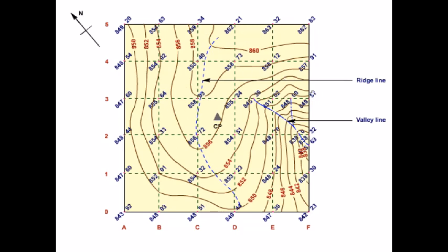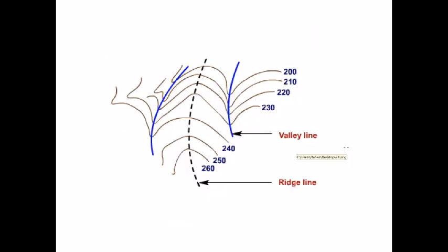So if you get these shapes on your contour map, you can distinctly tell what they represent. So like this over here, two V shapes. That means we have two valley lines, and in the center we have the other shapes, which are not that much steeper like we have in a valley line. So milder shapes and successive ones, they represent a ridge line, which is a mountain top, and over here you have a depression, which is a valley.